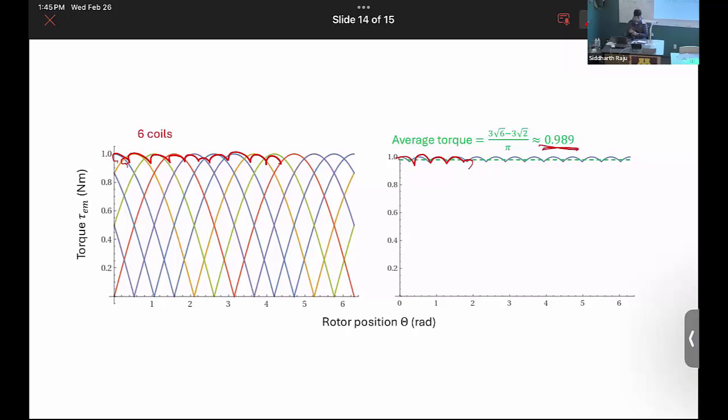There is another thing, which is something called cogging torque. When the rotor iron is aligned with the magnet, that is where the least reluctance is, and the rotor would like to stay at that point. So when you start a motor with very low current, the rotor won't rotate at all, because it likes to stay at that point where the iron is very close to the magnet.